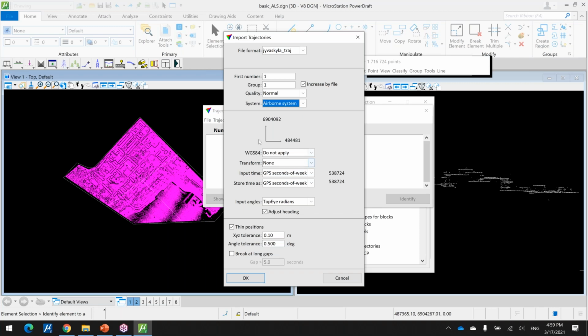We don't do any transformation, so just none, but in case you need to change the coordinate system, you can define the transformation, and then just by loading, there is a possibility to reproject. It's a user defined format for this trajectory, so we need to choose that we have degrees as input angles. For some coded formats, as for example Beta, I think, it recognizes the radians automatically.